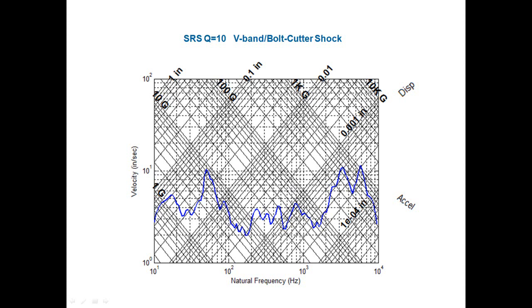But velocity, while certainly not constant with natural frequency, is more stable with natural frequency than either relative displacement or absolute acceleration. And that's another feature that makes the pseudo-velocity an attractive metric for characterizing the damage potential of shock.